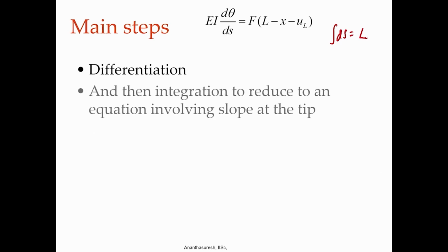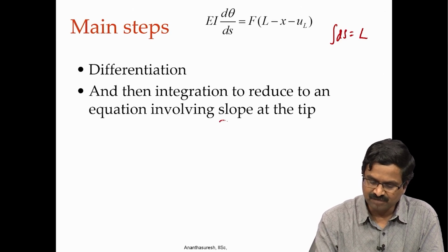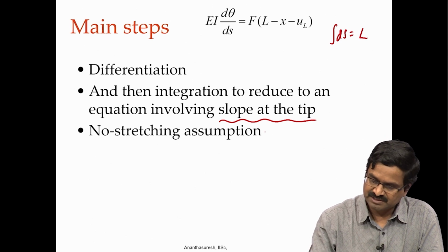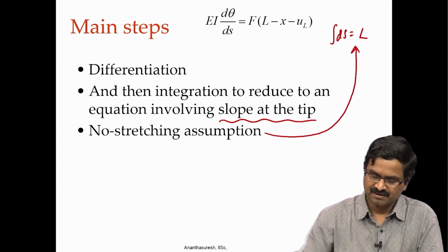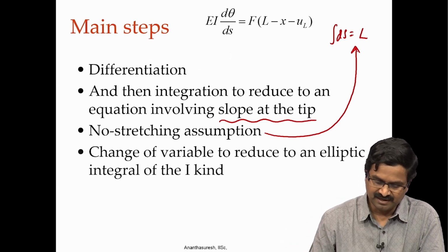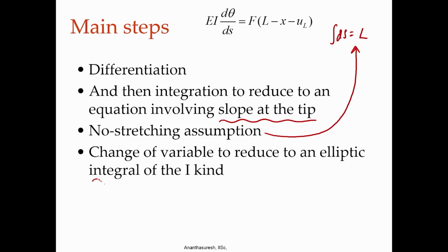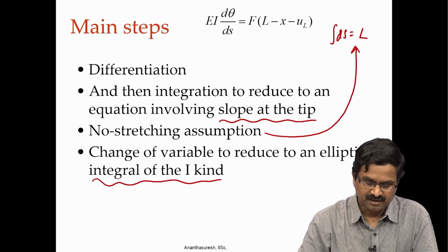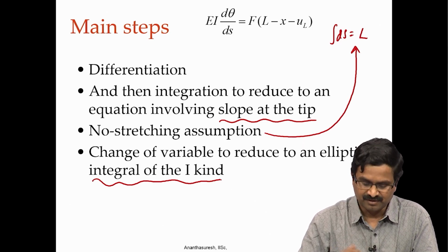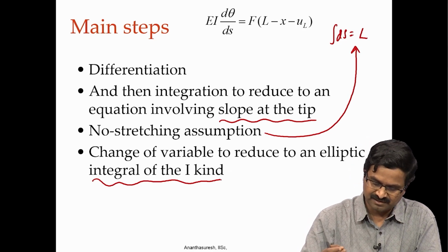We first differentiated and then did an integration after little manipulation to reduce to one equation involving only the slope at the loaded tip, and then we did this no stretching assumption, to solve for the theta L, and then we reduced it to elliptic integral of the first kind, and that we assume that these elliptic integrals cannot be solved in terms of elementary functions or analytically, but numerically you can do that. There are a lot of routines in MATLAB and other software to get this.